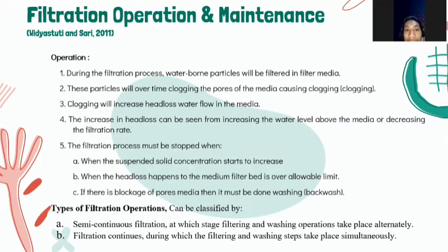Filtration operation and maintenance. Number 1. During the filtration process, waterborne particles will be filtered in the filter media. Number 2. These particles will over time clog the pores of the media, causing clogging. Number 3. Clogging will increase head loss of water flow in the media. Number 4. The increase in head loss can be seen from the increasing water level above the media or the decreasing filtration rate.